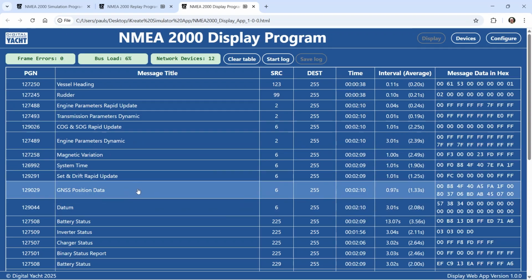It's about the nearest you'll get to being able to simulate, remotely, exactly what a boat's NMEA2000 network is like. So you get your customer, or if it's your boat, you log the data using one of our devices, and then you replay the log file. Now, obviously, this is sending out a lot of PGNs, and you wouldn't want to do this on a normal NMEA2000 network.